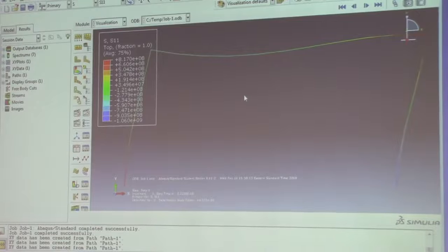So for this three-beam problem, what is the best way to do the seeding? Is it always the more elements the better, or for some beams you can just use one element? For some beams, we need to use more elements to do the approximation.